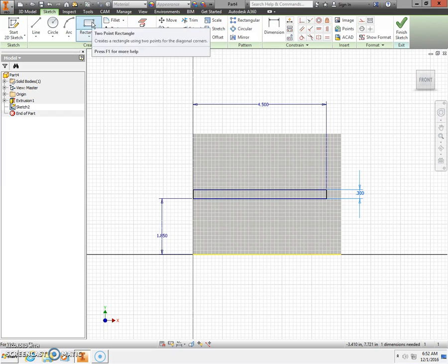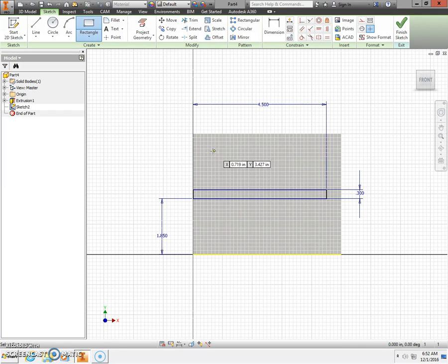Next, I'm going to select Rectangle tool again. Somewhere above the rectangle we drew, I'm going to click and stretch out another rectangle. This horizontal dimension is 3. Press the Tab key. My vertical dimension is 0.3 for the marble to roll in. Press Enter on the keyboard.